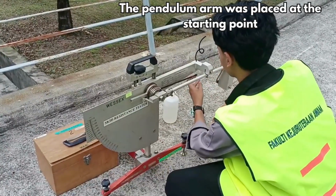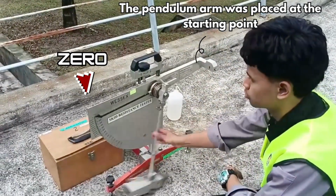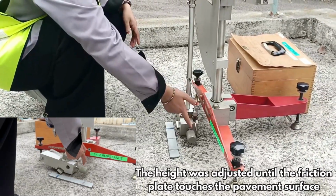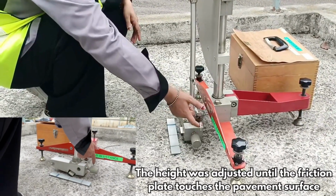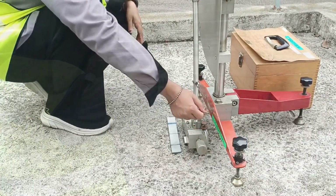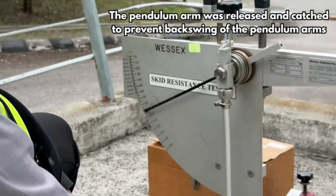Next, the pendulum arm was placed at the starting point. The maximum swing indicator was set to 0. Then, the height was adjusted until the friction plate touches the pavement surface. Next, the pendulum arm was released and caught, to prevent backswing of the pendulum arm.